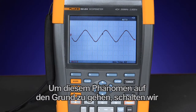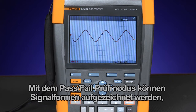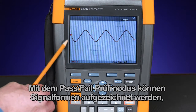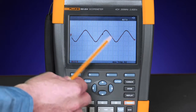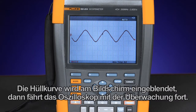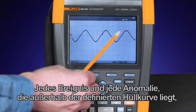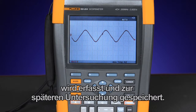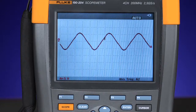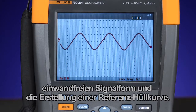To get to the root of the problem, we're going to use the scope meter's PassFail testing mode. The PassFail testing mode has the ability to capture the waveform in a known good state. It then stores the waveform into memory to use as a reference envelope. The envelope is created on the screen, and then the oscilloscope continues monitoring. Any event or anomaly that goes outside of that predefined envelope will be captured and stored in memory for you to inspect later.